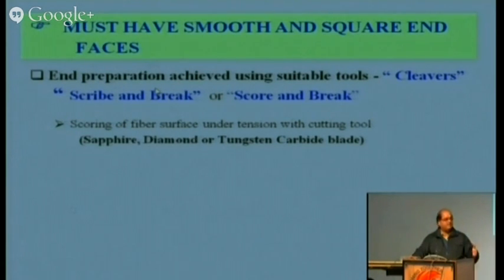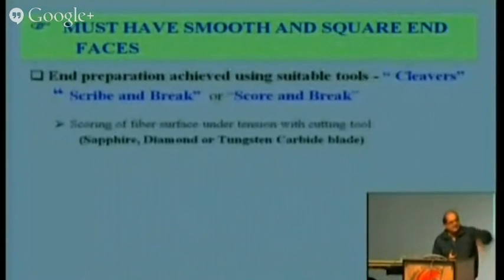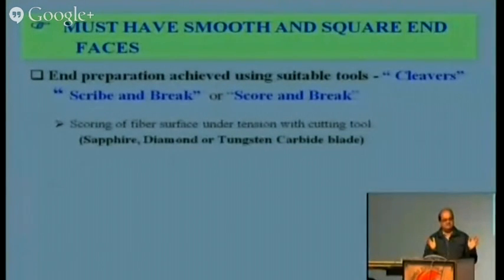You have to cut the fiber, and you know the fiber is made from glass. I hope everybody has seen the glass cutter. They use a diamond cutter just to make a line over the glass, and then they apply pressure. You cannot cut the glass by rubbing again and again. Only one line is sufficient; that will give you the best cut.